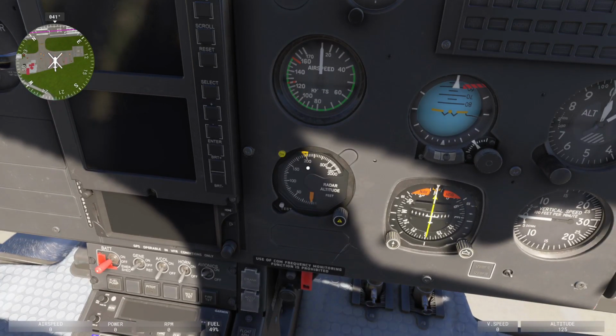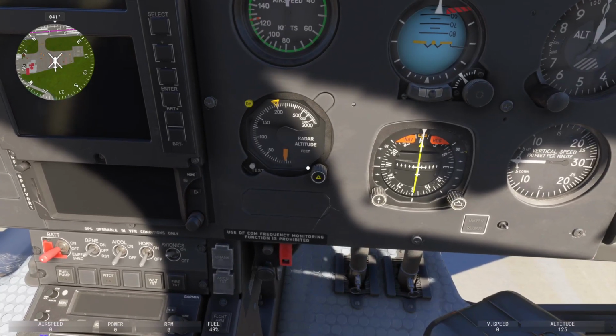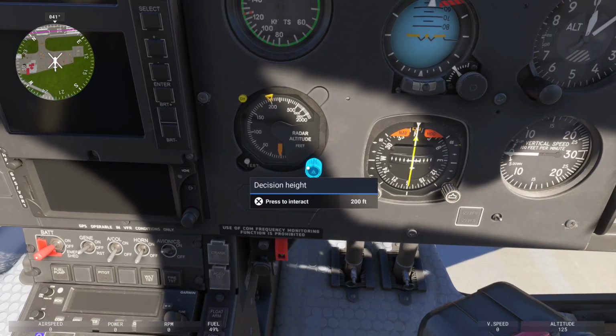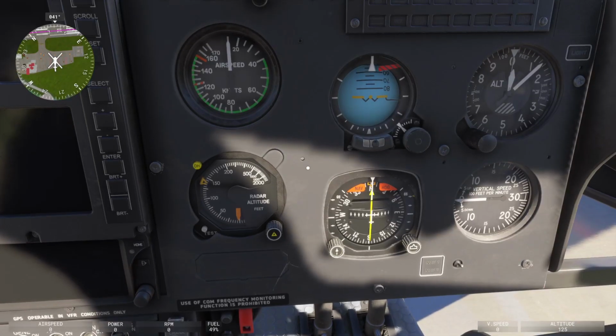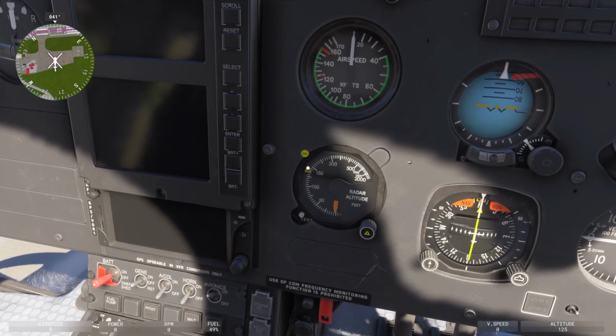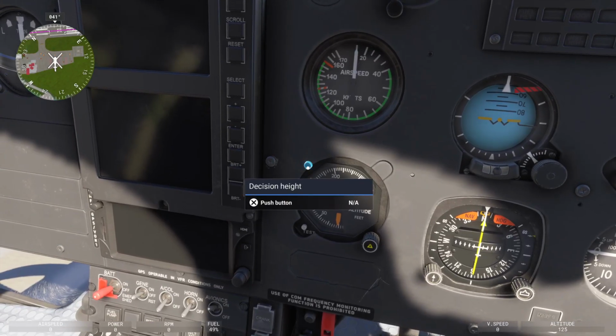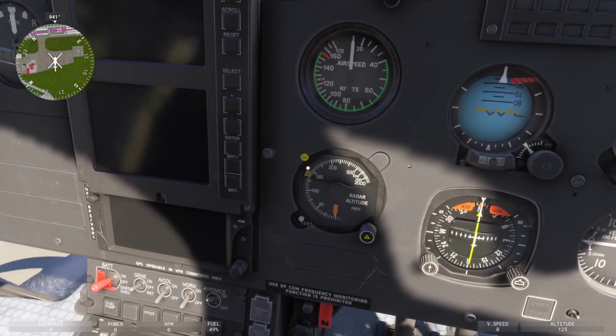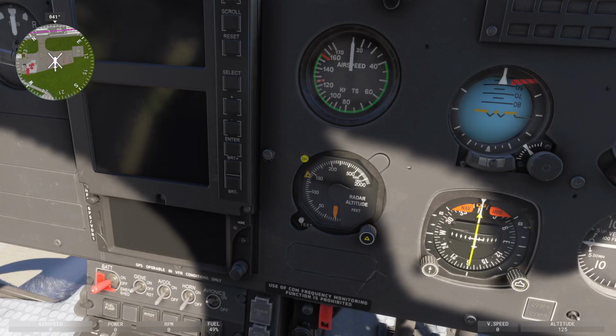This has got radar altitude. We spoke about that a minute ago, and this is accurate height above ground. And you can see here that you can set a bug. Now, in a lot of aircraft, this will signal potentially an audio signal. It will definitely give you an audio signal, and sometimes on some aircraft it will give you a light and a warning as well. On here, when I've tried to set in that bug, it's not done anything. Okay. And that's basically our decision height. We want to know if we're going to go beneath that.